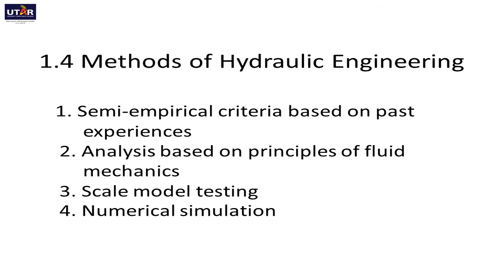The third method is to make a scale model, such as a small model of a dam, to test the intended functions of structures and modifications, such as the spillways from a dam. Then the fourth method, which is developing with advancement of computational techniques, is to simulate the effects of planned structures by numerical simulation. In this course, we cover all these methods except for the third one, the model testing method.